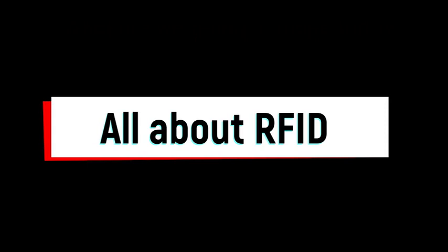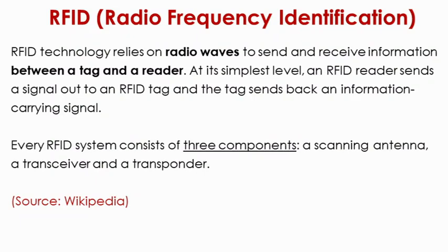Now let's see what RFID, radio frequency identification, is all about. RFID technology relies on radio waves. First important point to know: it receives information between a tag and a reader. So there needs to be a tag and there needs to be a reader. The RFID reader sends a signal to the tag or card, and the card or tag sends the information back to the reader. It consists of three components: a scanning antenna, a transponder, and a transceiver.